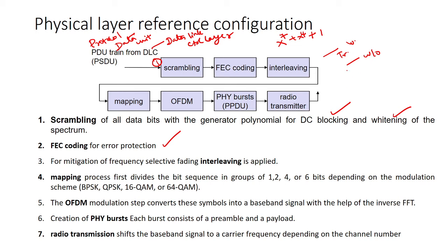With respect to this interleaving, if there is any burst error from the forward error control, it passes through the interleaving. The interleaving improves handling of the burst error by making the burst error controllable with respect to codes. So the burst error will be controlled with respect to codes in the interleaving stage. After the interleaving stage, it is passed through the mapping process.